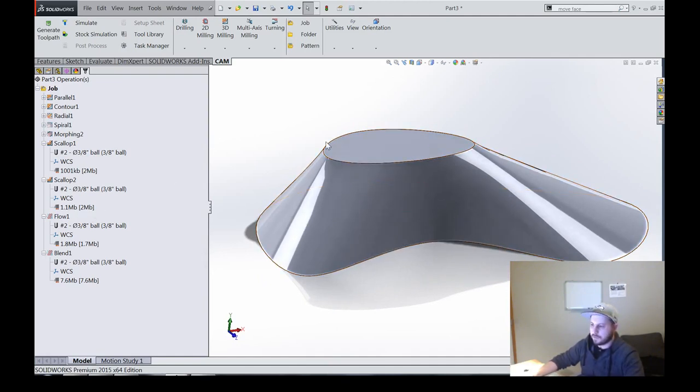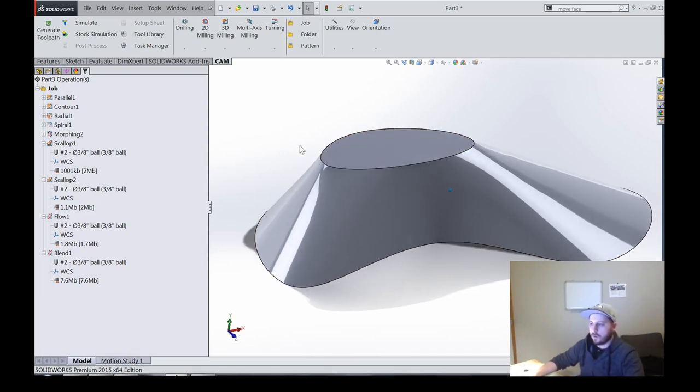Where the problems come up is when you have two surfaces that link together but were built using different methods, maybe one is a generated fillet and one was a loft or a sweep. In any case, the UV lines on them aren't aligned.